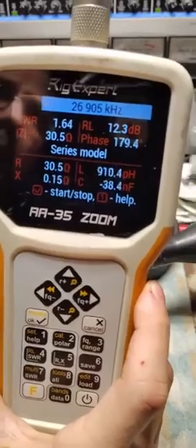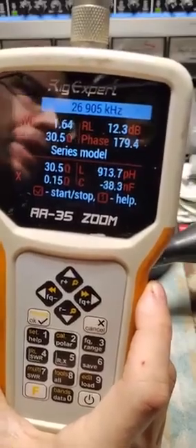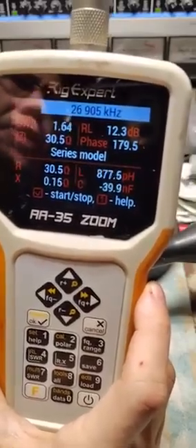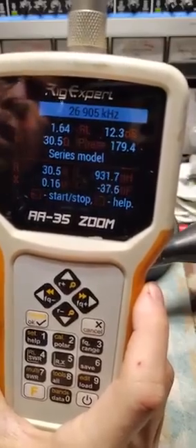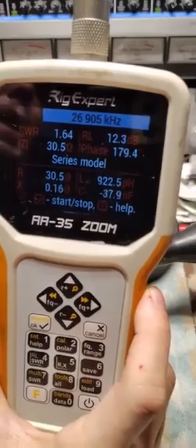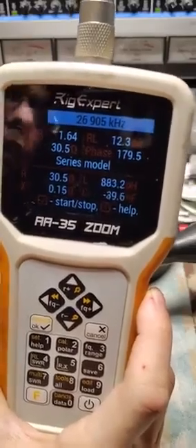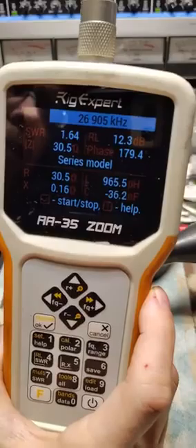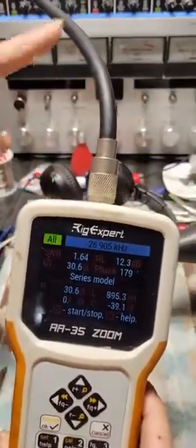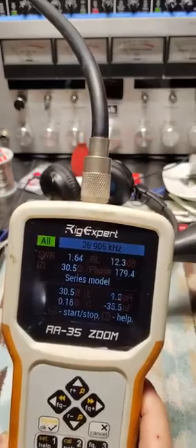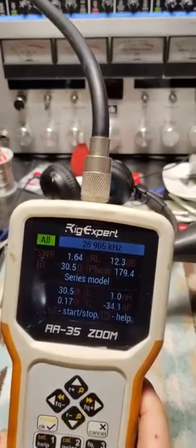It makes perfect sense to me, because resonance has absolutely nothing to do with your SWR. You can have a resonant antenna that is in the thousands of ohms. Will that present a good SWR on a 50 ohm feed line? Absolutely not. But does it mean that the antenna isn't resonant?